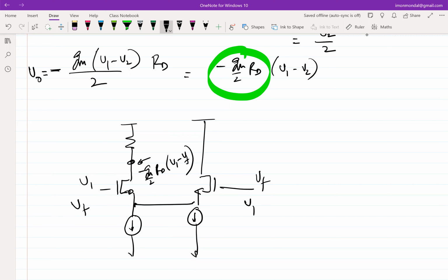So I just have to take the same circuit, flip, and not connect in the way we started the common source amplifier. Now you have two independent inputs. You can connect either input to any of the input ports without being concerned about loading, because now you have two transistors, you are looking into the gate, right? And none of the transistors will be loading the previous case because the input impedance is effectively infinite.